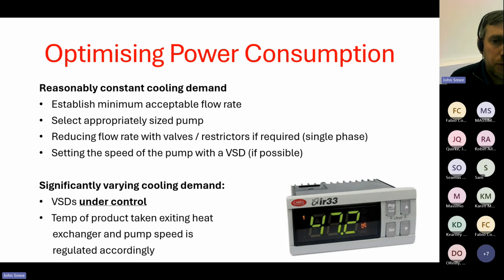So what you would do there is figure out your minimum flow rate to give you the results that you're looking for, and select an appropriately sized pump. And I've seen this time and time again, that guys will just say, oh, what do I need? 50 litres a minute. Oh, this one does 100 litres.